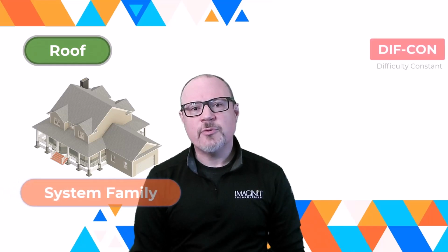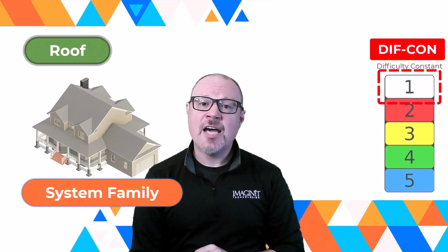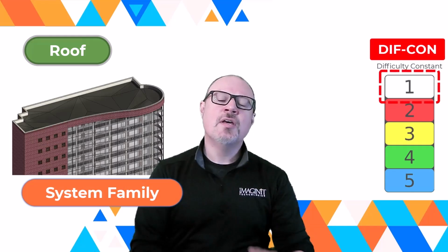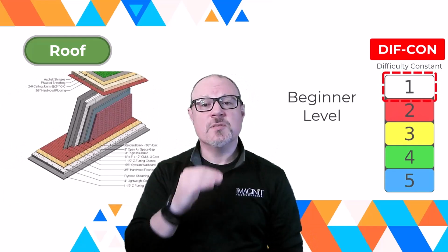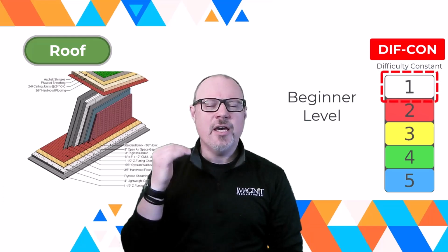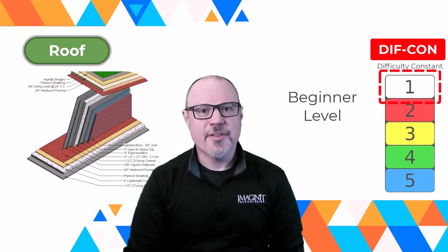Sorry about that. Today we're going to be talking about roofs in the Revit software and the ability to stack material on top of each other, making different roof types with different materials and thicknesses that add up to the total thickness of the structure of the roof, as well as membranes, topping, and roof structure. Let's take a look at it together.